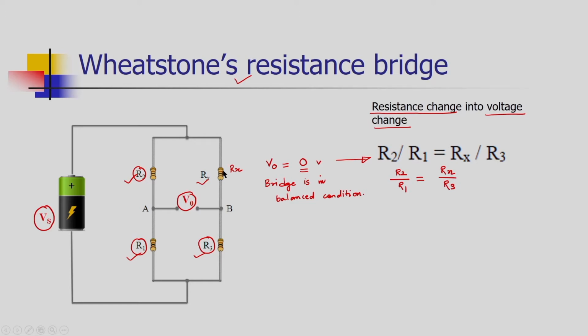Now, in the application of the Wheatstone resistance bridge, we attach this Rx to our strain gauge leads. So, let us attach our strain gauge at Rx.